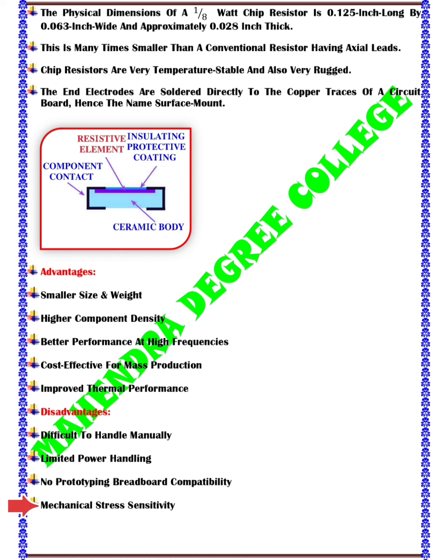Fourth one. Mechanical stress sensitivity. It means the solder connections for surface mount devices are more prone to damage from mechanical stress, thermal cycling, or vibration, especially if not properly supported or if the printed circuit board is subjected to repeated flexing.